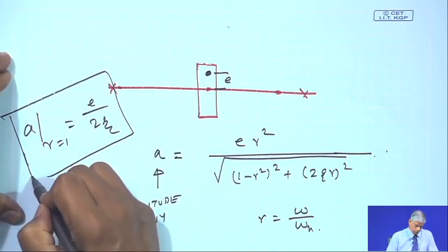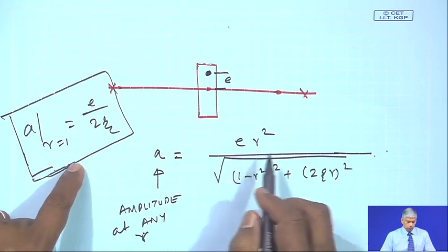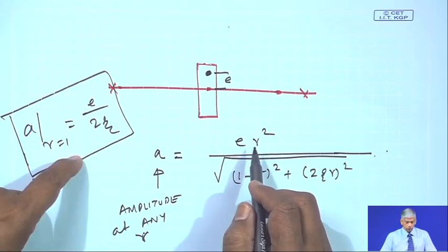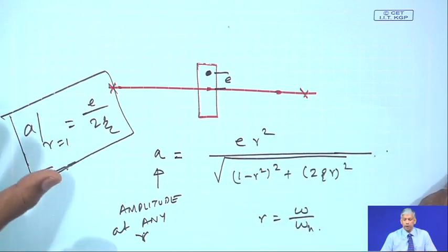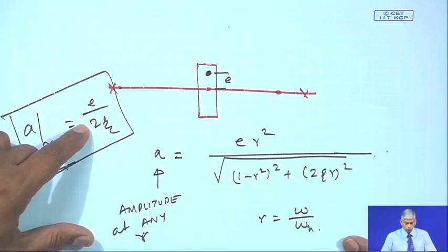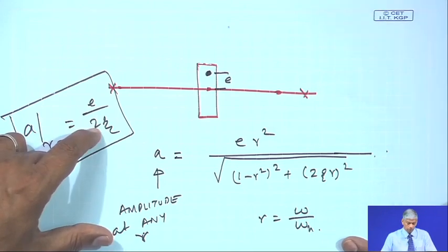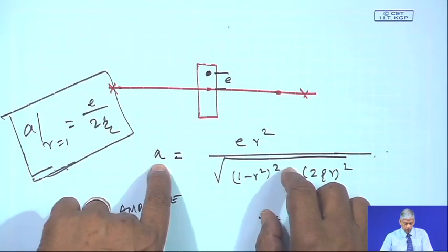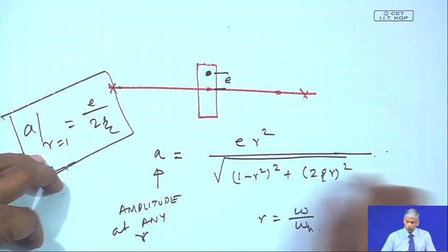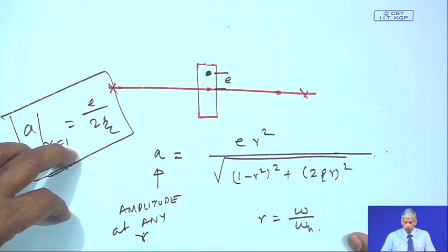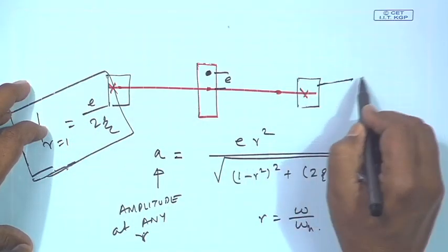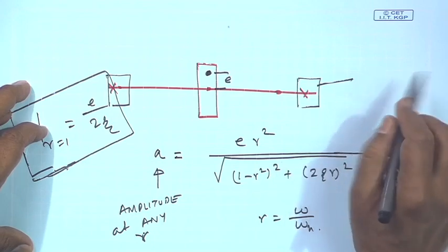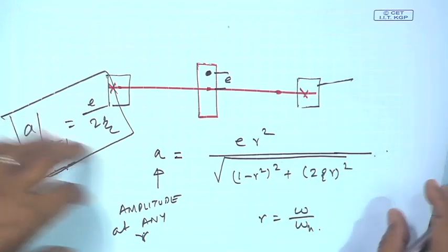So, this is an important conclusion from vibrations, that at resonance all the amplitudes are controlled by playing around with the damping. So, we can introduce damping in the system to reduce this amplitude, and in rotordynamics people design systems wherein they can have some external damping played around at the bearing stiffnesses, and we will come to this later on.